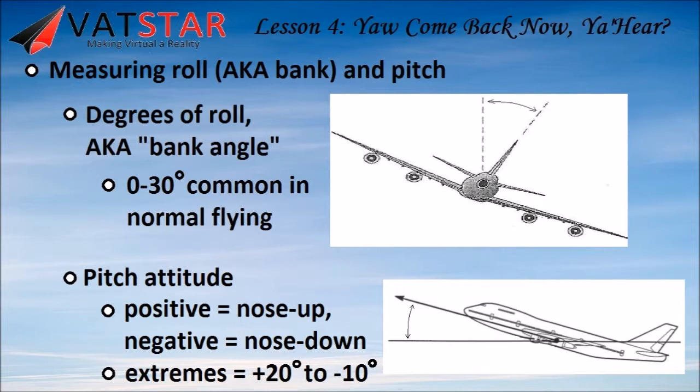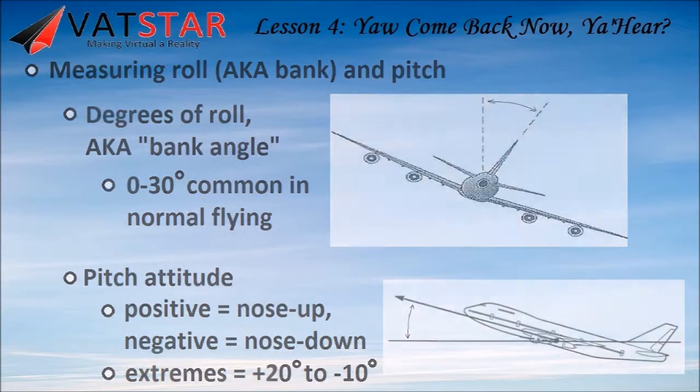You'd normally only go to around 15 degrees nose up during takeoff, and then after that, the most you'd usually use is like 7 or 8 degrees. Descents, you're probably not going any more nose down than about 5 degrees most of the time. But believe me, the passengers feel exaggerated pitch effects, so 20 degrees nose up probably feels to them more like 50, and any more than 5 degrees down gets them started reciting prayers.